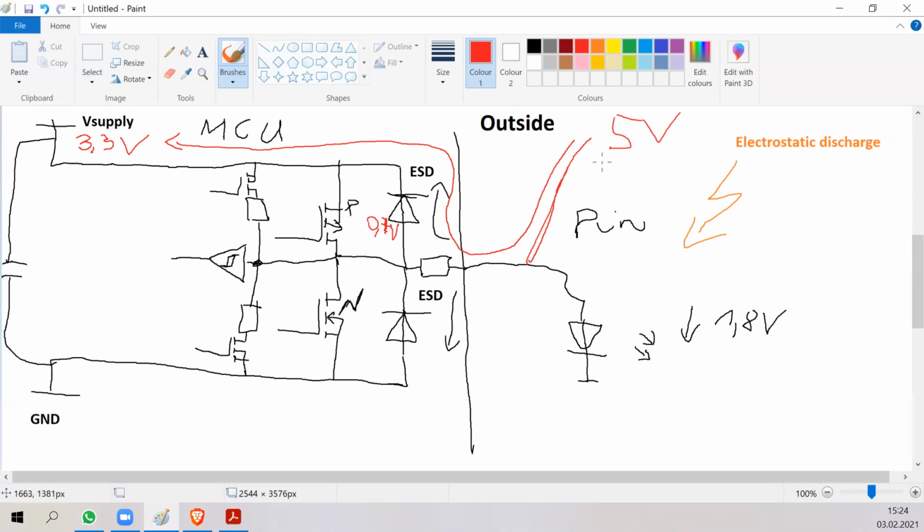And for example, if you didn't connect it directly to 5 volts, but you connect it to some weak signal, which is 5-volt biased, maybe your microcontroller doesn't even burn immediately. It's just that after a couple of seconds, if the current is big, then this diode heats up, burns, and then the current goes into the processor and burns the internals.